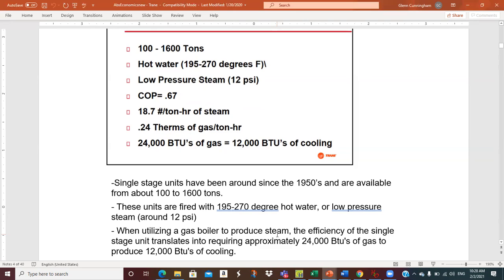If our required input in the steam is 17,758 thermal energy divided by 0.85, that's about 20,900. So that's like 0.209 therms. So depending on the efficiency of your boiler, you could modify this.